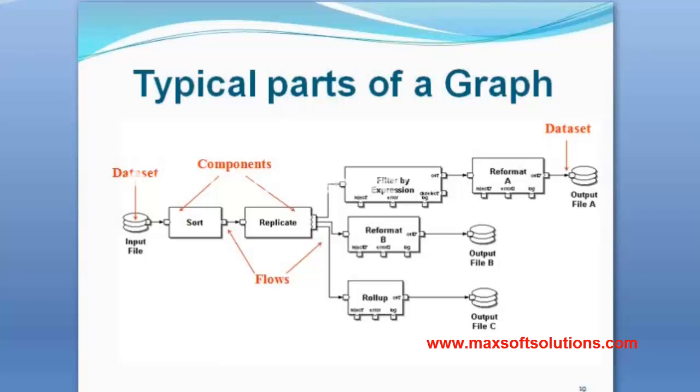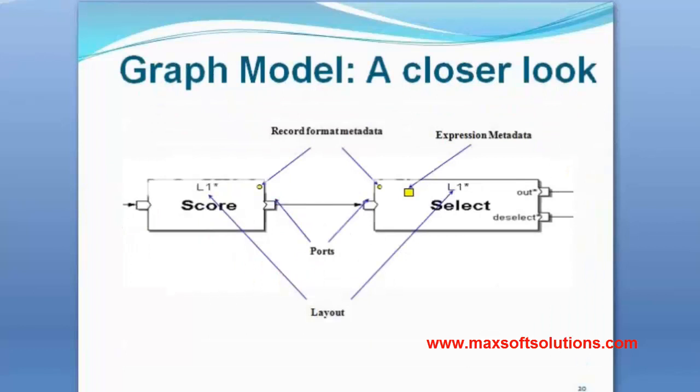And the second part of the question: what are the components which can accept multiple inputs? To find that out, take a component and mouse over its input port. It will show, in brackets, gather. If gather is present on that input port, then it can accept multiple inputs in a single port.